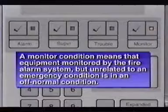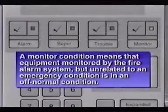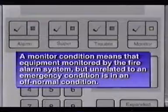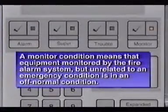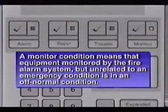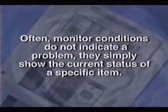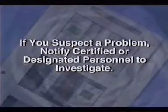A monitor condition means that equipment monitored by the fire alarm system but unrelated to an emergency condition is in an off-normal condition. Some typical causes of a monitor condition include open or unsecured doors and disabled fan systems. Often, monitor conditions do not indicate a problem, they simply show you the current status of a specific item. If you suspect a problem, notify certified or designated personnel to investigate.